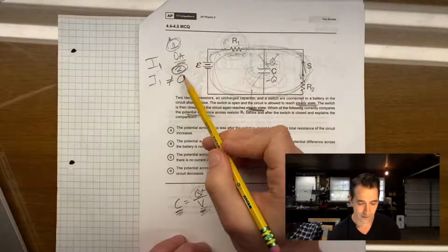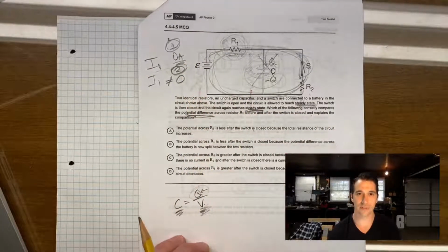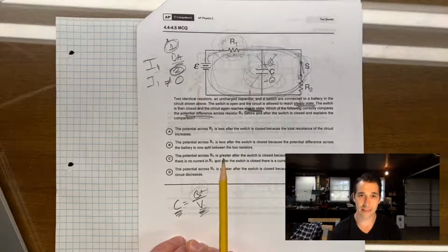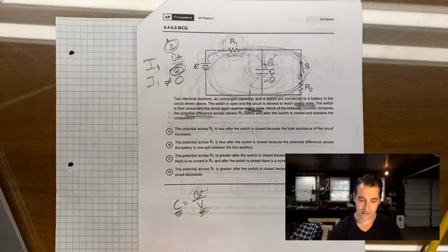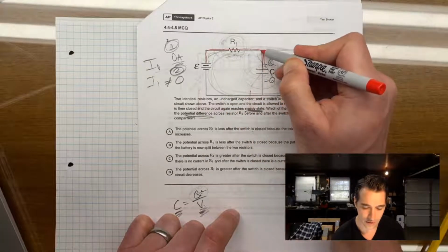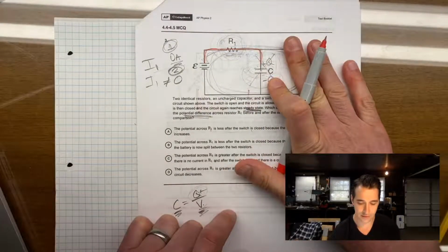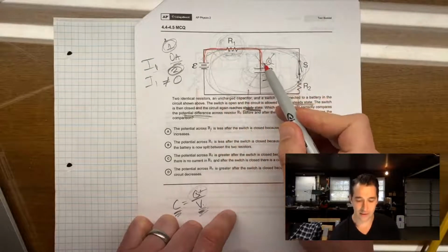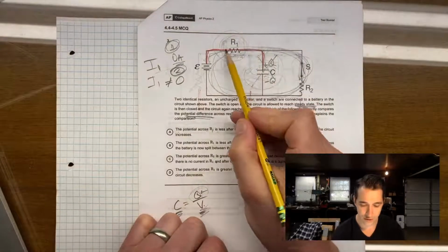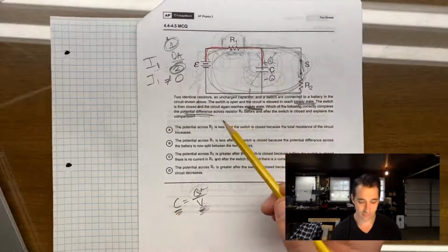If we know that we have current in the second situation, but there's no current in the first situation, if there's no current flowing through there, what does that mean? It means that everywhere in this side has all reached, this is situation 1. This is not involved. Everywhere in here has the same potential. So in situation 1, the voltage difference across resistor 1 is actually 0.